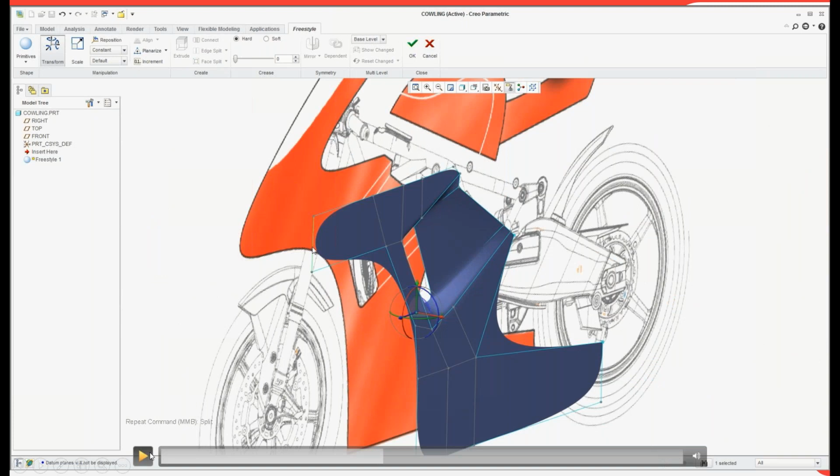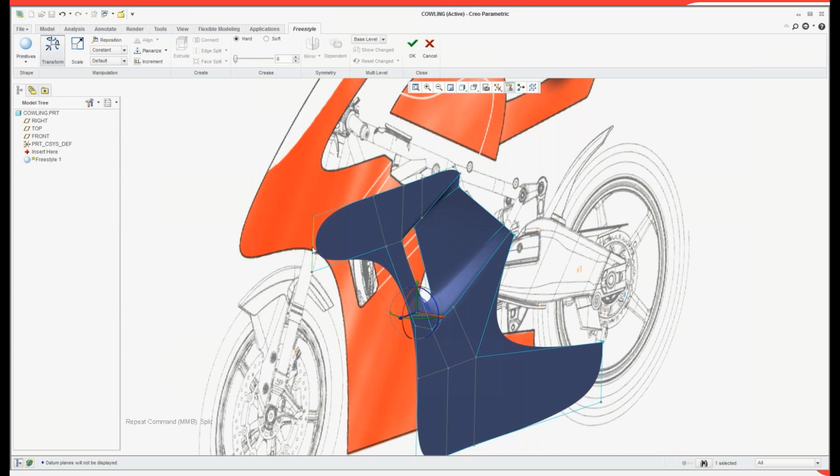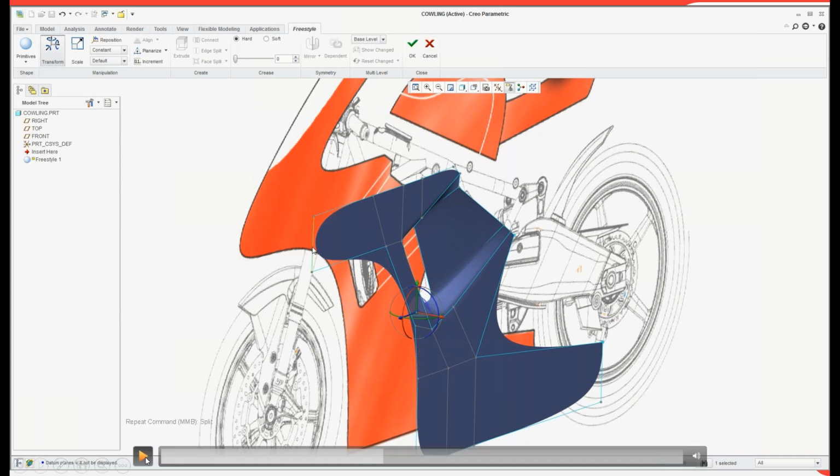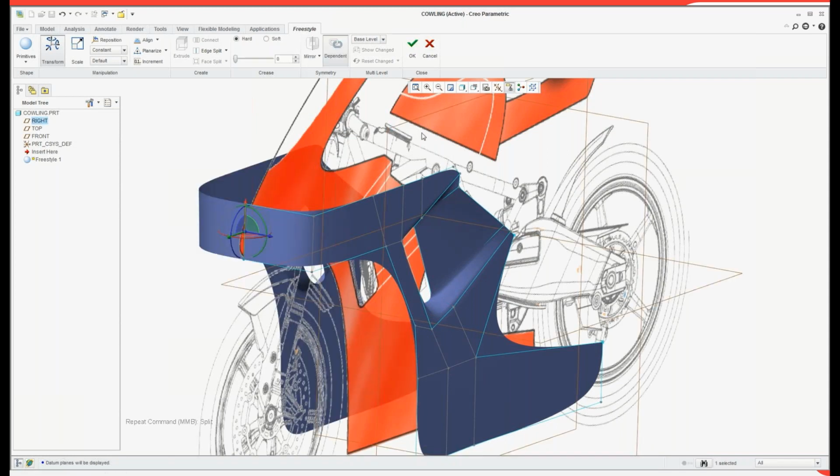This is important. If there is a mirror kind of thing in product designing, you just design half of the side of that component and just mirror it. So the complete modeling which happens on one side of the plane will duplicate to the other side as well. And any changes made on one side will also reflect on the other side. So it will make the user or designer very fast. Changes made on one side are automatically reflected on the other.